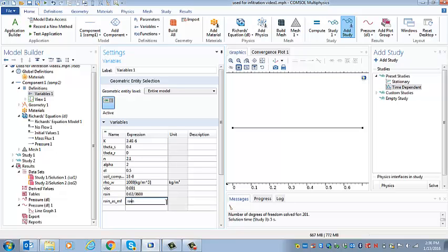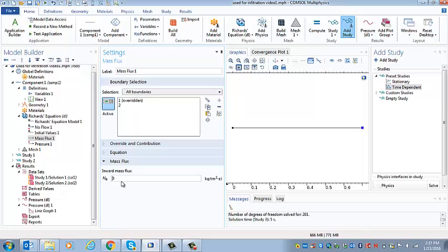So that's the volumetric flux, and then we can define rain as MF, mass flux, and that will be this rain, which is a volumetric flux, multiplied by rho W, which is the density of the water. That says kilograms per cubic meter for the units, so we can get that into the right units, and this would be good to do as a check if we put some parentheses there, and then in square brackets we'll specify the flux of the rainfall as meters per second. If we do that, then you can see we've got the correct units for rainfall as a mass flux. And we can put that here, rain as MF, as the upper boundary condition.